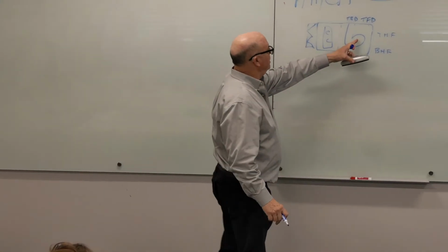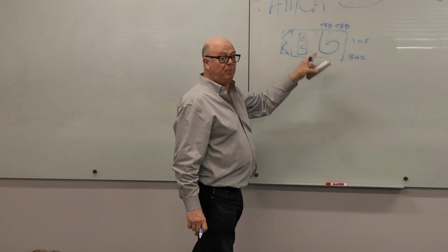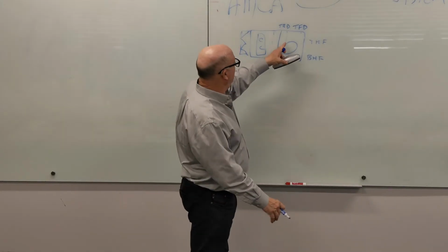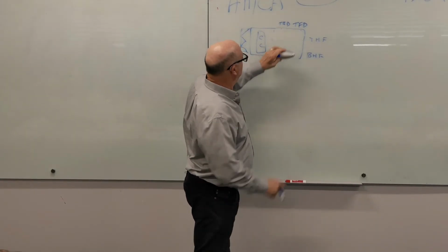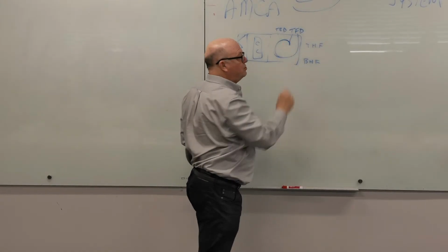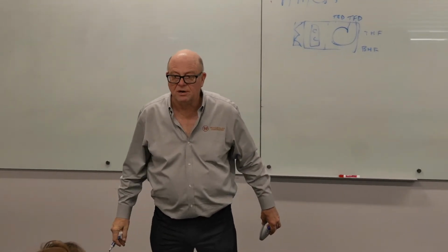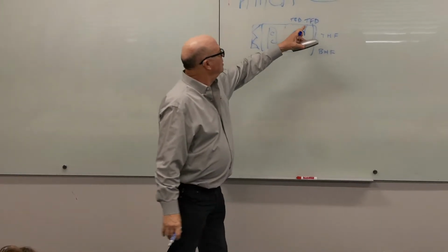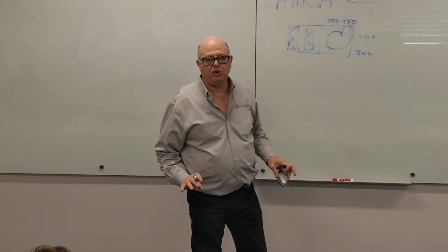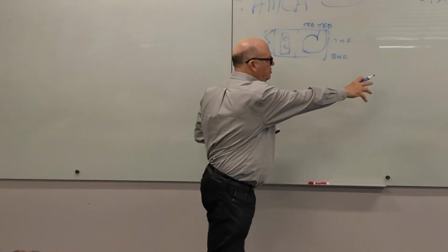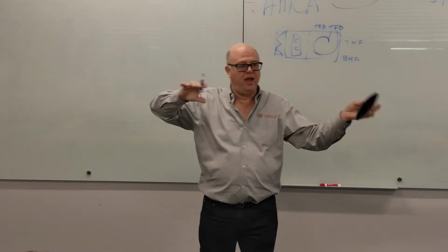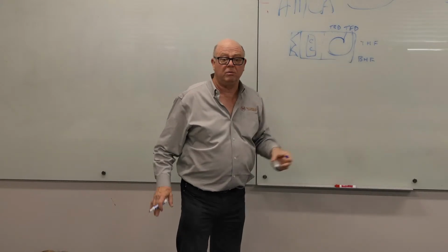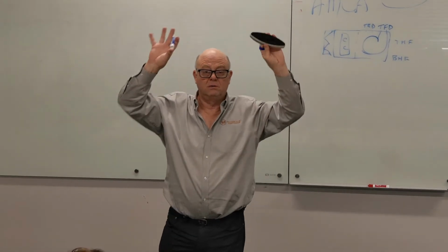Because if I give you a submittal and it shows this, and I ship this, it's your problem if you approve the submittal. On the other hand, if I give you a submittal that shows this, and we ordered it wrong, and we ship this, that's on us, if I'm the rep. Okay? So, we've now talked about 3 things you've got to review. You've got to review the configuration on a loose fan. You've got to review the hand of both the coil and the motor, and if it's an air handling unit, you have to review the discharge.